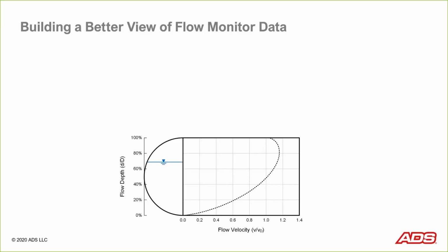The reason for that is if you think about the early 20th century, a lot of the pipes that were being designed and built were some of the larger sewers in some of the larger cities, and they were built using a lot of different cross-sections. So you think other cross-sections, non-circular sections like egg-shaped pipes, horseshoe or basket handle, there's a whole variety of those. So you would often find a group of hydraulic elements curves in these textbooks that would show how the Manning equation changed with different pipe cross-sections. I actually like that. It helps show the physical context of that pipe.